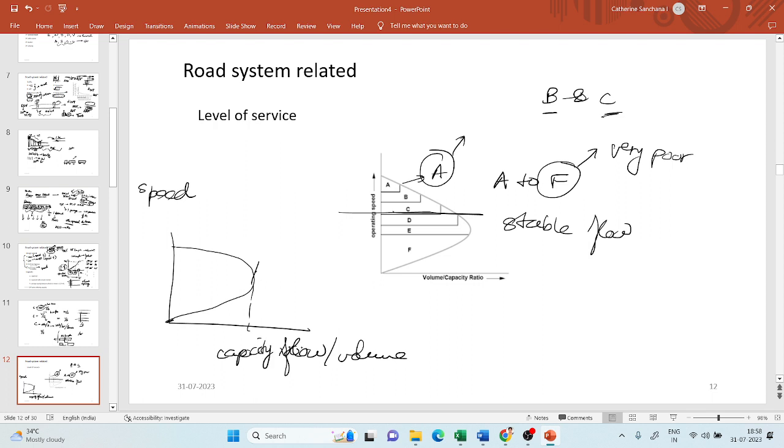If you remember correctly, I said that I will stand and count the number of vehicles passing a cross section, and that is the volume. And the maximum volume that I get is what I will call capacity. So, in this graph of speed versus volume, the maximum value is capacity. And if you see here, let us understand this graph. If the volume is zero, it can mean two situations. It can either mean that my roadway does not have any vehicle on the road,